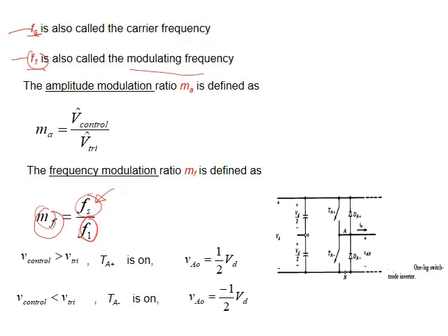Also, let me define MA, the amplitude modulation, to be the comparison between V control and V triangle. Just a minute, it reminds me of the same discussion for triggering thyristor and rectifier circuits, and for controlling DC-DC converters by pulse width modulation. We discussed them before. Yes, it's almost the same.